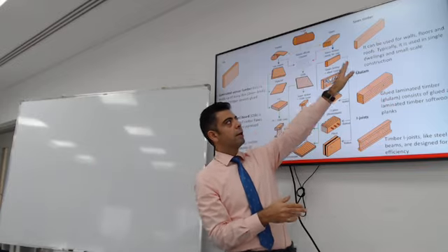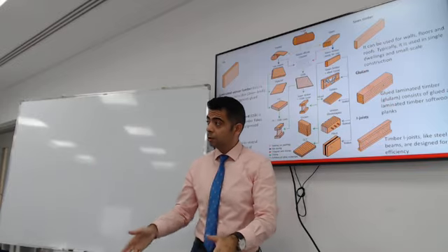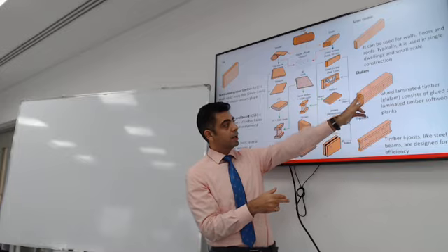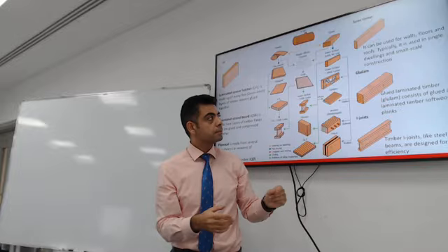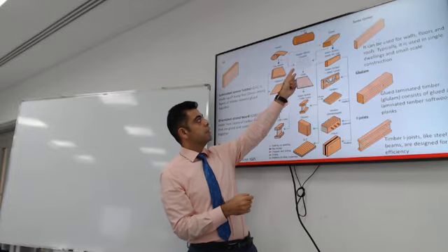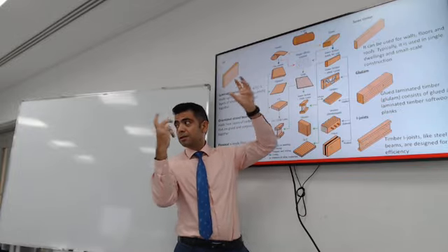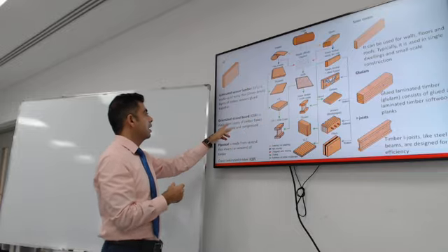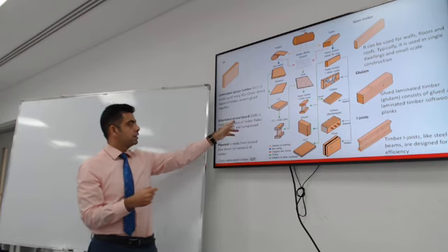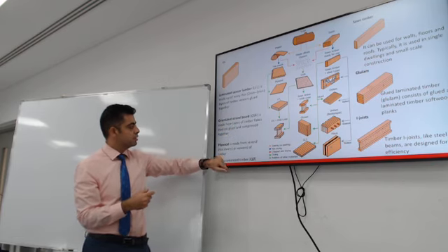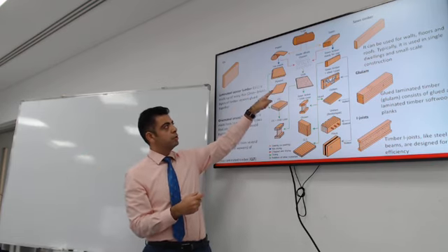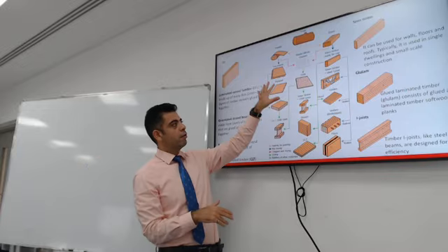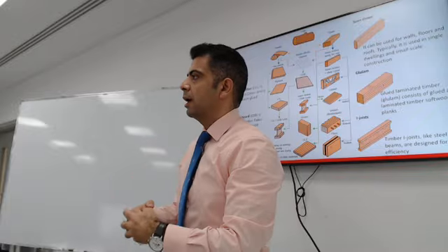With just sawn timber, you can create floors and columns. You can glue them together, just like that, and you create glulam. From the waste of cuts, the chip wood, you can create OSB, oriented strand boards. From the sheets, you can create plywood, gluing the sheets together. And then you have all these products to build a building.